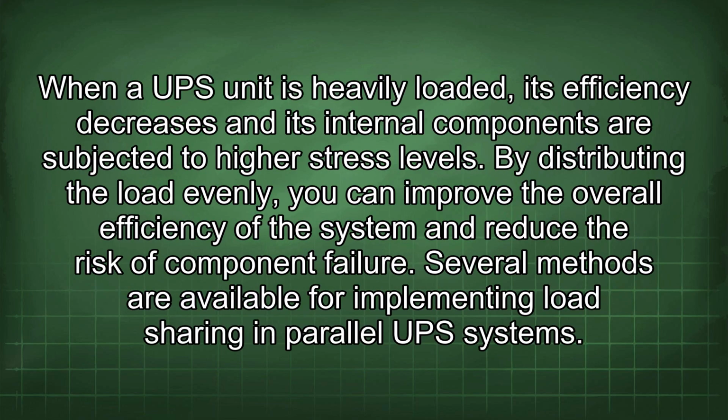When a UPS unit is heavily loaded, its efficiency decreases and its internal components are subjected to higher stress levels. By distributing the load evenly, you can improve the overall efficiency of the system and reduce the risk of component failure. Several methods are available for implementing load sharing in parallel UPS systems.